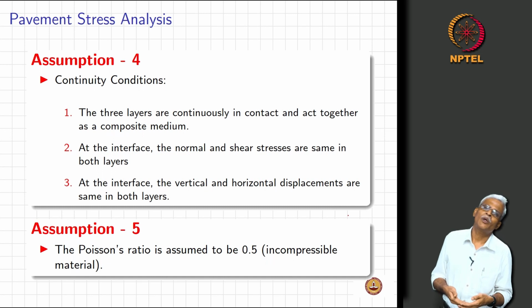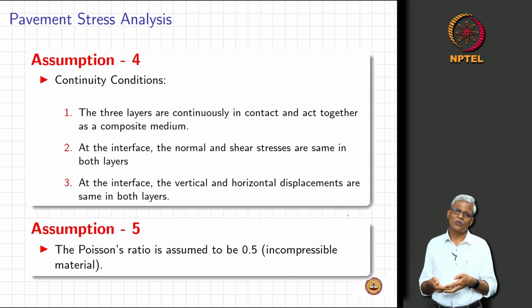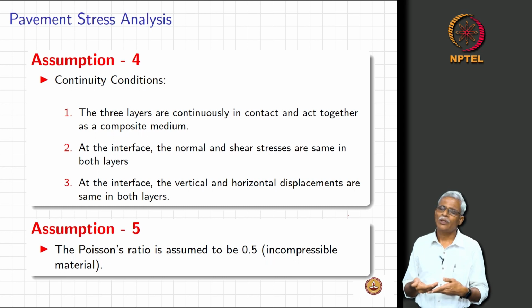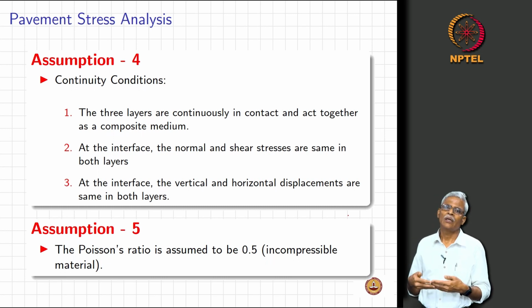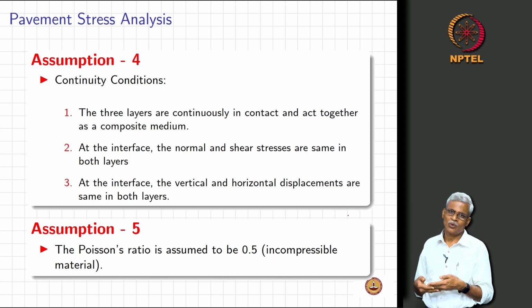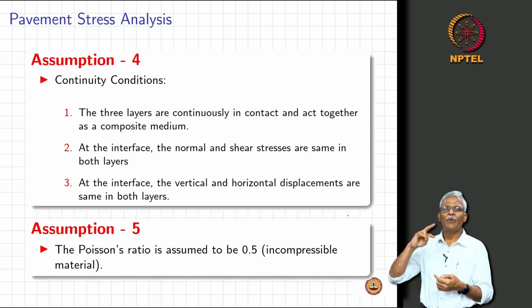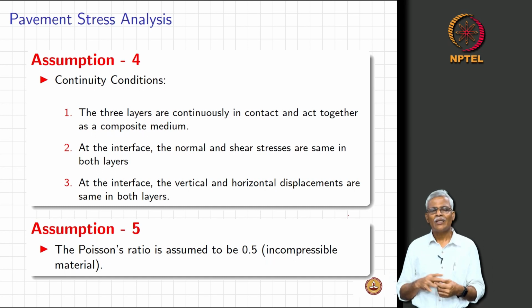Then on top of it, what are you going to have? You are going to have your sub base. Now, what are you going to do between these two layers? Are you going to do anything? Nothing, you are just going to lay it, and on top of it you are going to have a base course. Then when you start your asphalt layers, you will have a small prime coat there, and between two bituminous layers a tack coat is going to be applied.